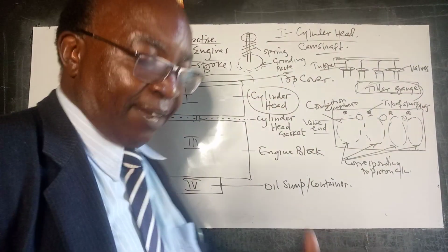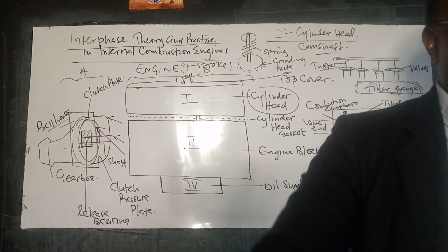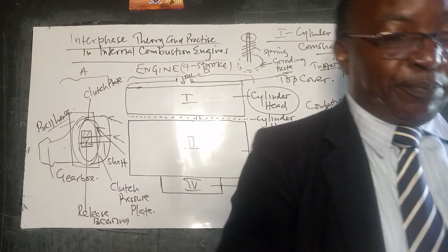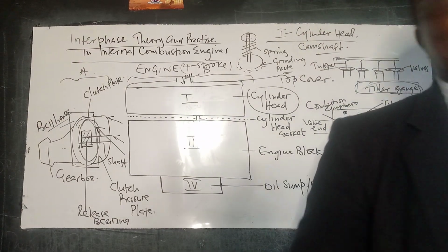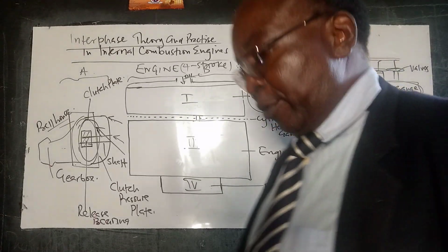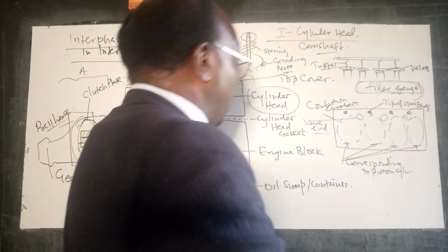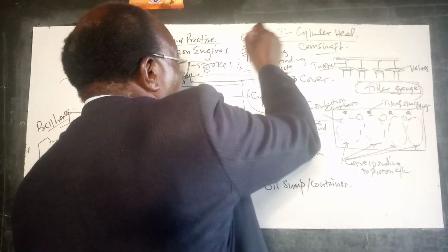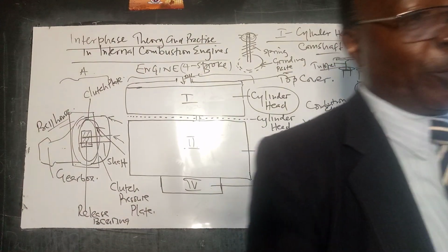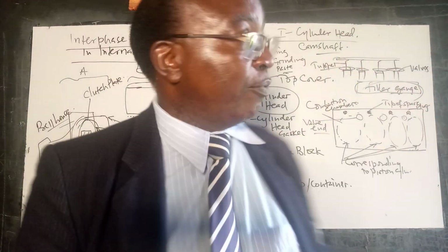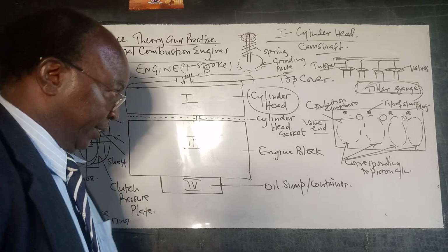So we have seen the camshaft and the tappets, for which you have to do tappet clearance. We have the valves. If you are rebuilding your engine, then you have to grind the valve using a paste. It has both coarse and fine pastes, so that you get it perfectly neat. Then you can wipe it with gasoline to clean it so that it's perfectly fitting. And when it's mounted, there are locks for it, and there's a spring there. Fixing it is quite a bit of work. So that gives us our cylinder head. So we have an idea what this cylinder head is.